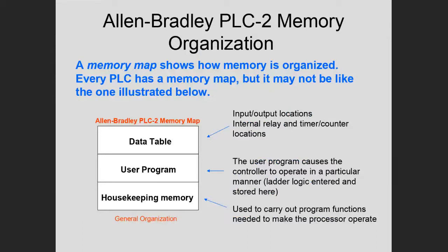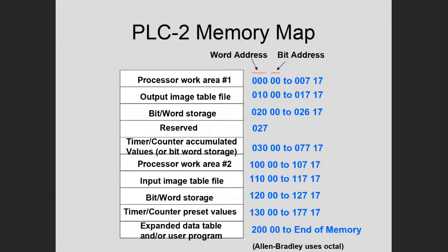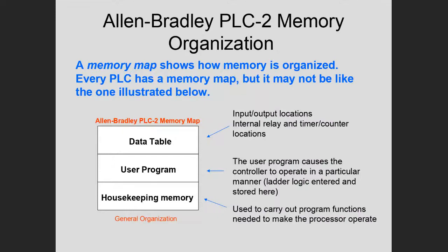All PLCs have a memory map. They're not all organized like this. I mean, this detailed organization depends on who makes the PLC, the manufacturer. But you can think of any PLC memory map as looking like this. All PLCs would have a memory map that consists of these three pieces. So this is the one I want you to remember for exams, quizzes, and just as you go through and use the program. So there's three sections of memory in any PLC.